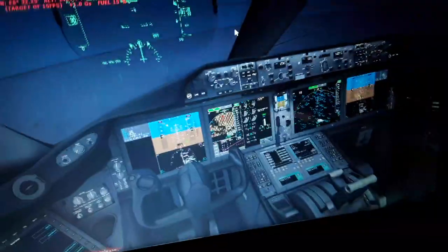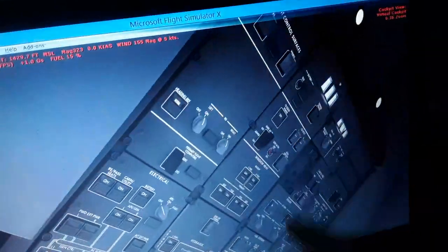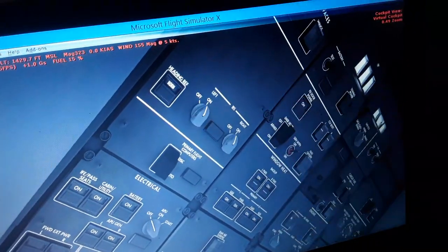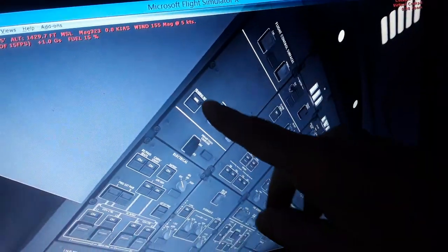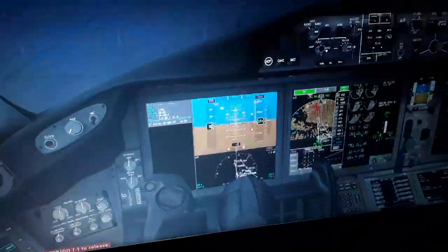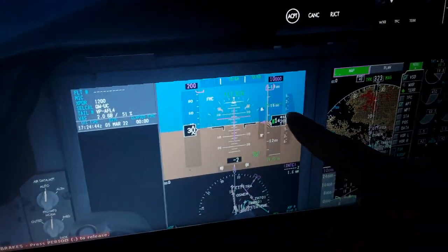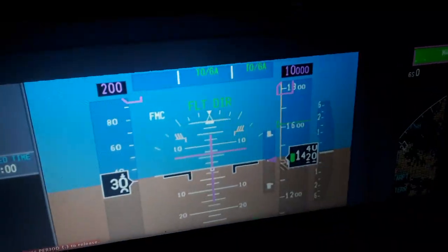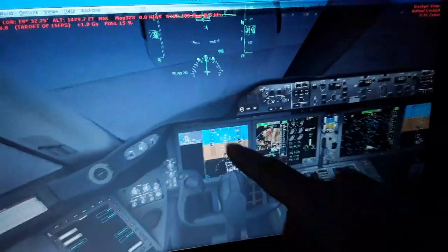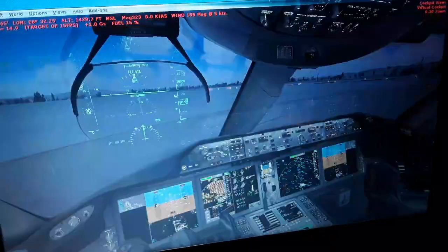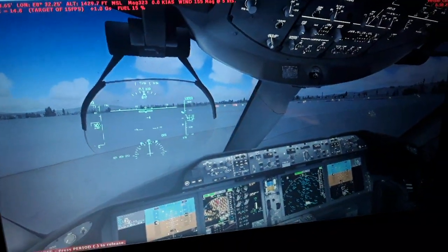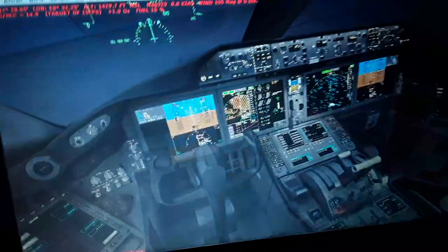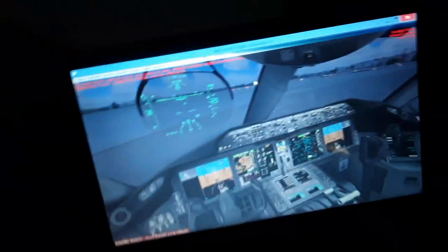We have also the air data computer over here in the overhead panel. It displays all GPS receivers, laser gyroscopes, magnetic north pole, pitot static and pitot dynamic for the airspeed, dynamic airspeed, and pitot static barometric altitude, vertical rate of climb, descent, laser gyroscopes, radio altitude, also angle of attack as we fly, temperature, barometric pressure here. So this is the air data computer, alignment of the aircraft.